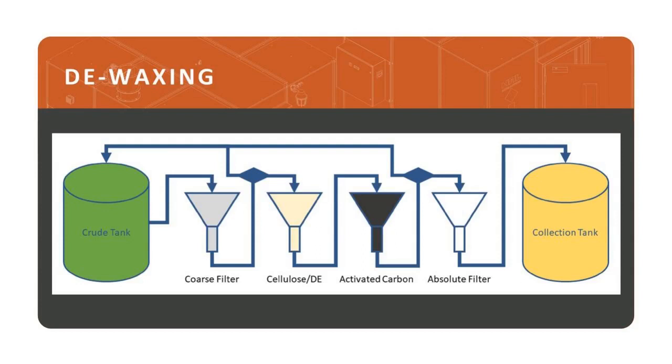And what happens is, as the butane or hydrocarbon mixture, along with those cannabis extracts, sits in that dewaxing chamber, the same process occurs. So the waxes start to coagulate. They separate out of that mixture. And then as you can see on the screen here, what you can essentially do is pass that mixture, the super cold solvent and cannabis extract, through a series of filters, typically following the same philosophy where you start with a higher micron, coarser filter before moving into a finer, as displayed here, an absolute filter, to remove those lipids from your products.